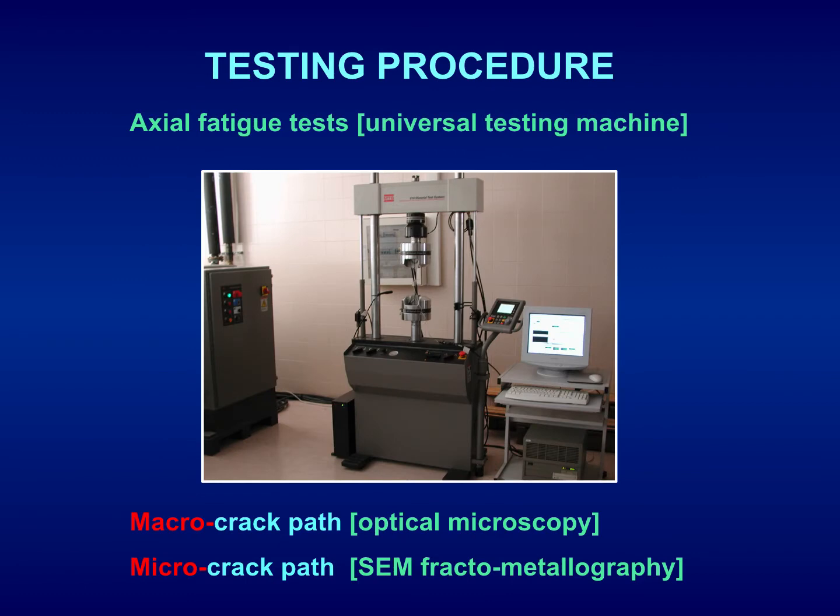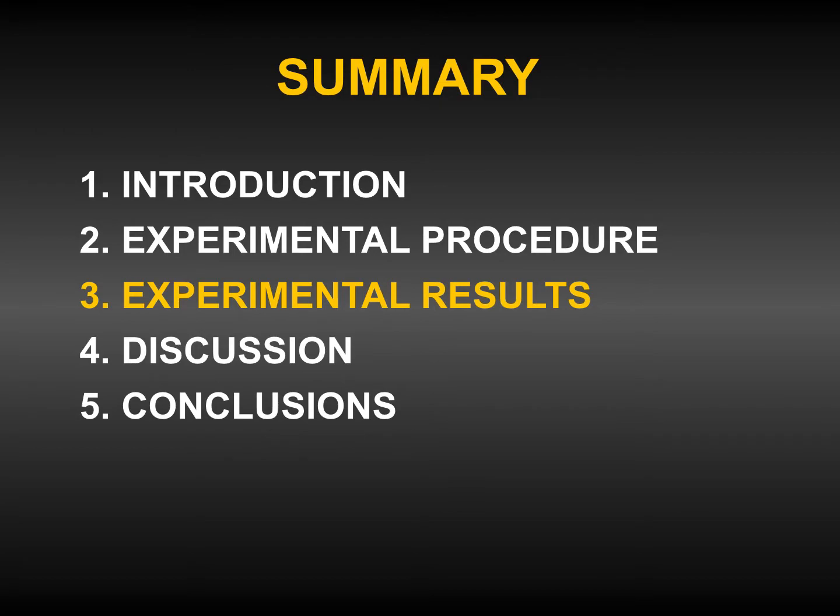The testing procedure: axial fatigue test in a universal testing machine, to look for the macrocrack paths by optical microscopy and the microcrack paths by scanning electron microscope fractometallography.